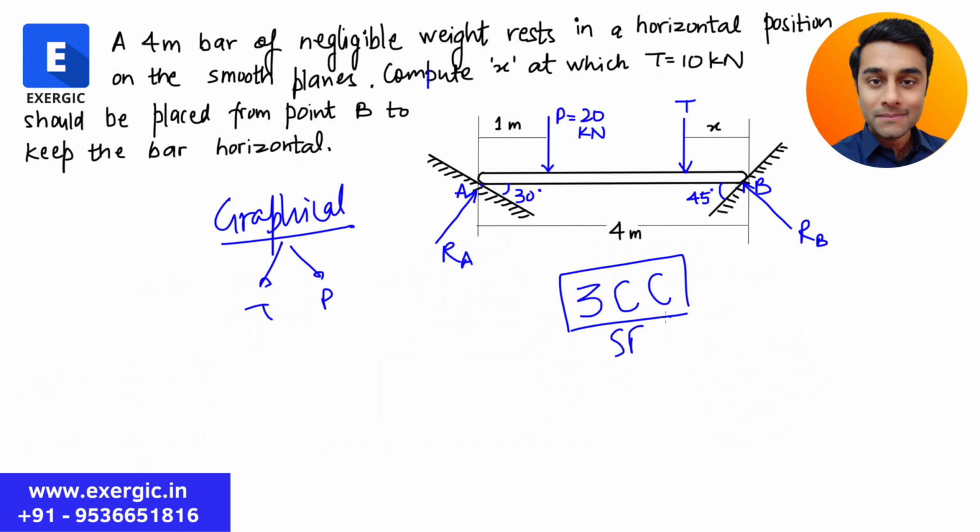And similarly, if we have more than 3 forces, say 4 coplanar forces in static equilibrium, they have to form a closed polygon, which we were referring to as a force polygon. Sir, in this case there are 4 forces acting, so it must form a polygon having 4 different sides, right or not?